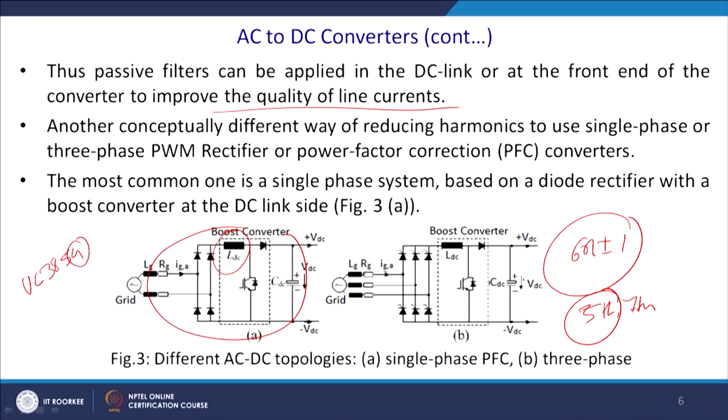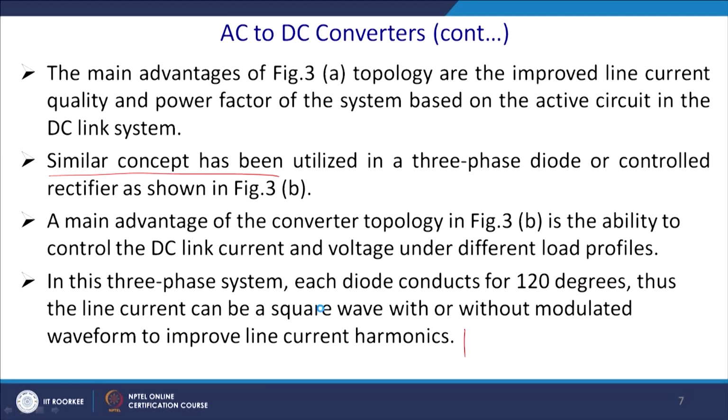So, this is for the 3 phase, but since it is difficult to generate an envelope in 3 phase, this kind of technique may not work fine, and ultimately we have to go with the fully controlled rectifier to get power in a bidirectional way. Mostly we may also need to put a little bit of filters here to eliminate these frequencies.